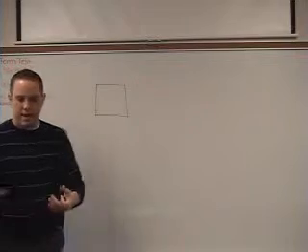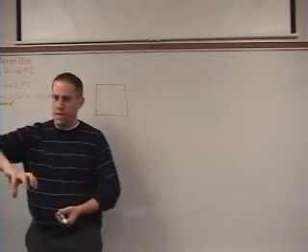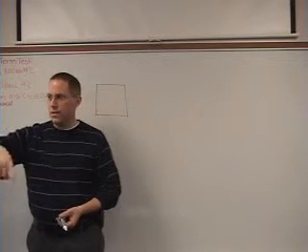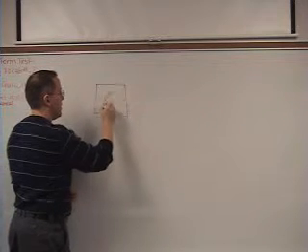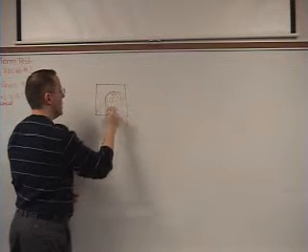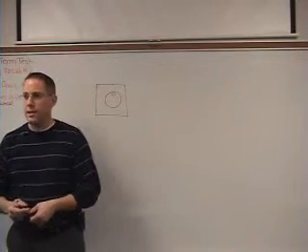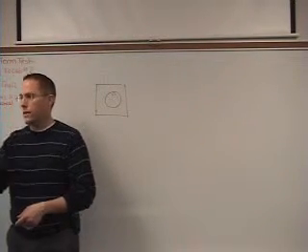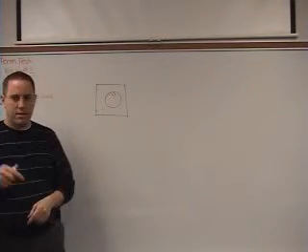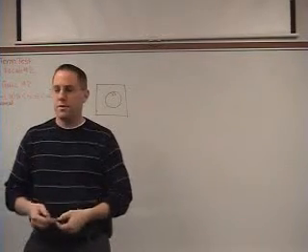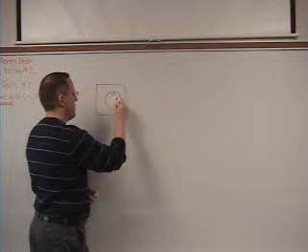you just take an X-ray cassette with film in it, and there's a top, just like those little toys you used to have. You spin it, and it spins around. Well, you put that top on here, and it's got a little hole in it, and then you spin it and you take an X-ray of it. After you take the X-ray, you're going to see a circle on your X-ray film, and it's going to have some dots, because this little hole, as it spins around, allows the radiation to pass through the hole. So you basically look at your X-ray and see how many dots there are.